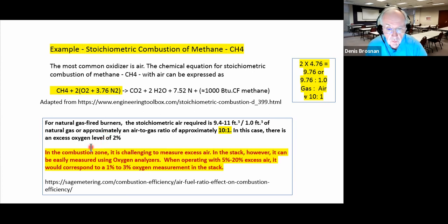Okay, so typically we use oxygen analysis on the flue gases from time to time to make sure that we're combusting all the fuel. The fuel costs us money, so therefore we want to make sure we get all the heat out of it. We don't want any unburned fuel coming out of the kiln. That would contribute to greenhouse gases and be considered pollution.